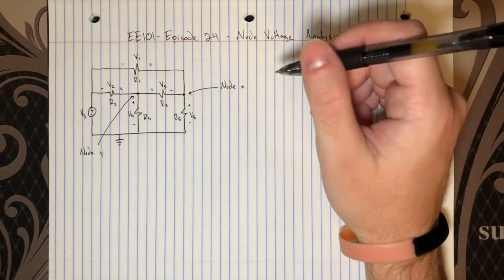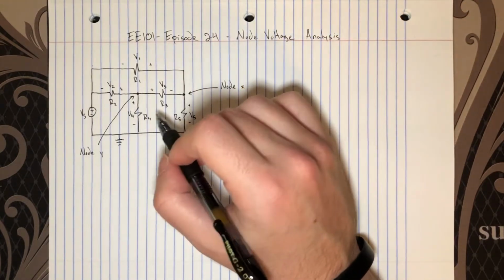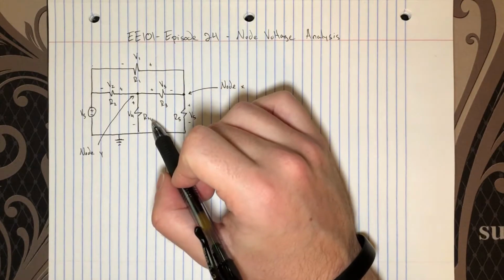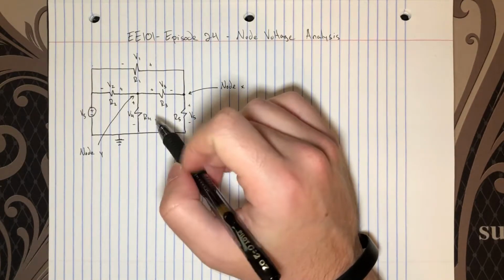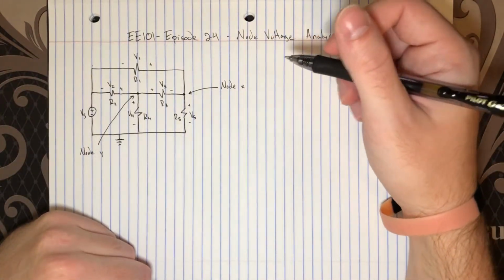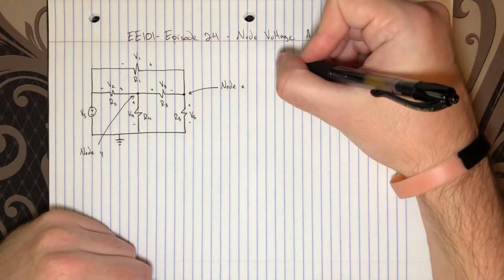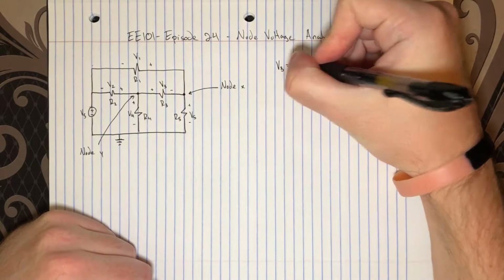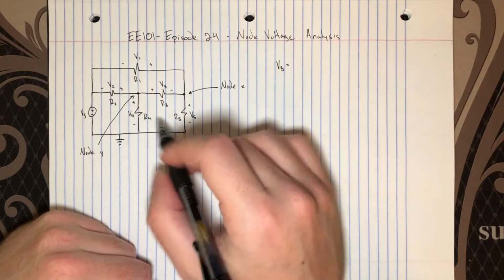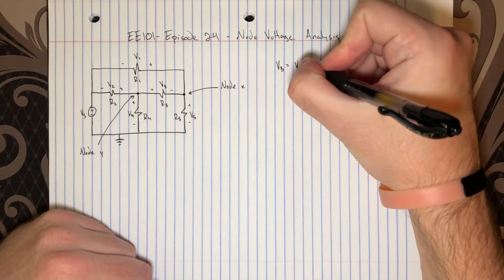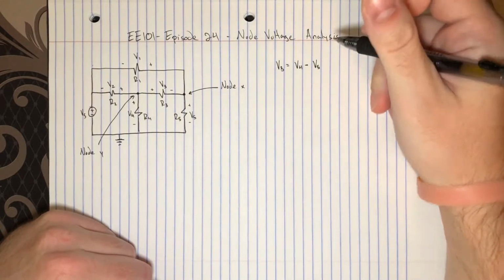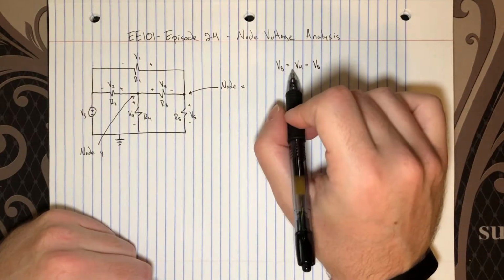Now, if you remember Kirchhoff's voltage law, I can look at any loop in the circuit, so I can ignore all this other business and just look at the loop of resistors R4, 3, and 5. So it should be pretty easy to see that, given the way we've assigned our voltage polarities, V3 should equal V4 minus V5. And this is totally familiar.